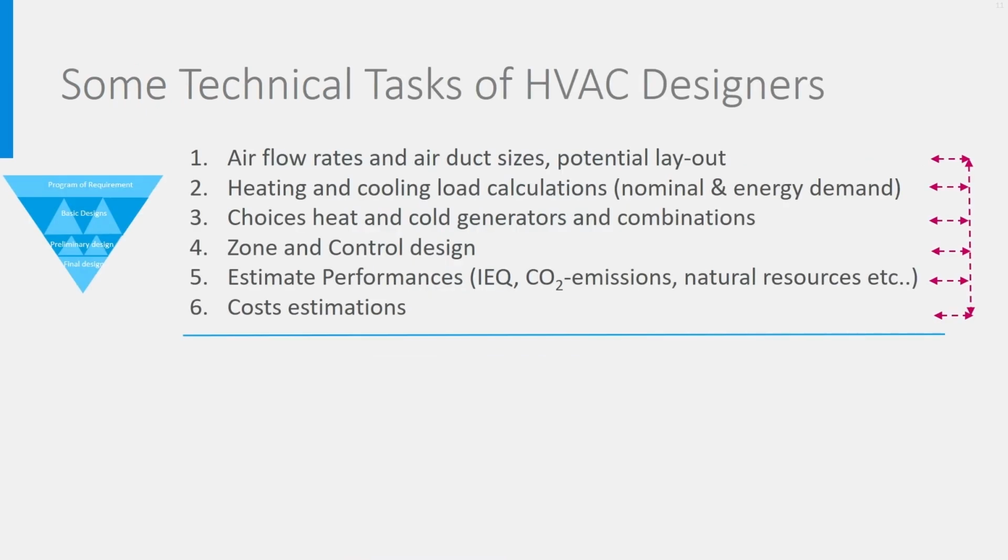Finally, a few words about some of the technical tasks that the HVAC designer will encounter. The order of the tasks does matter in this slide. During the design phase, even before thinking about the energy supply or the level of insulation, you will make estimates of the size and layout of ducts. This is because this is essential to the work of the architect. Then you will make heating and cooling load calculations with simple tools in the basic design and advanced ones in the later phases. This is the step where decisions are taken about insulation, for instance.